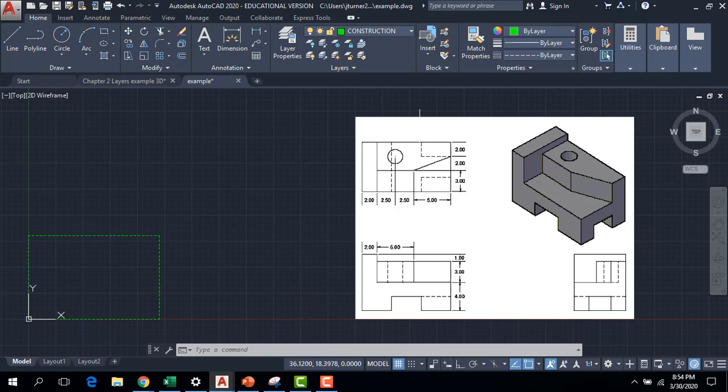Now maybe I want to draw the top view. The top view is going to have a length of 12 and then a height of 7. So for this one, I'm going to start my rectangle command again. I was at 0,0, and this was where I was at 0,8. See my coordinates over here? The coordinates will not show up unless you have some kind of drawing command going. So here's 0,8, and maybe I want to put a space of, I don't know, 2 or 3 behind it. So I'll go from 8 to maybe 10, and I'll start at 0,10.